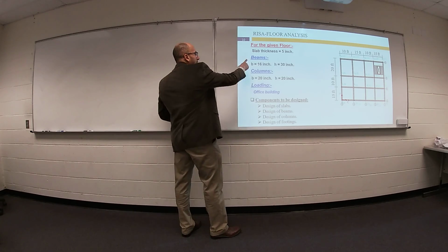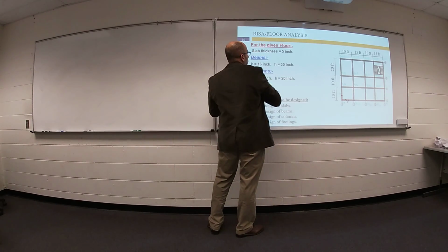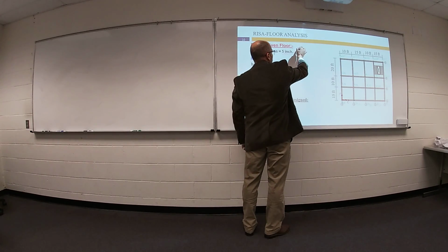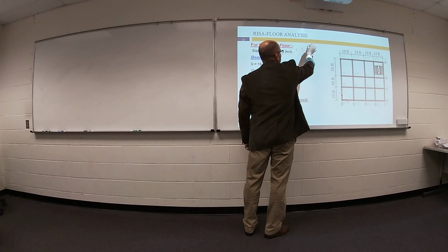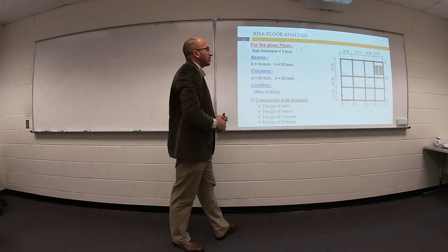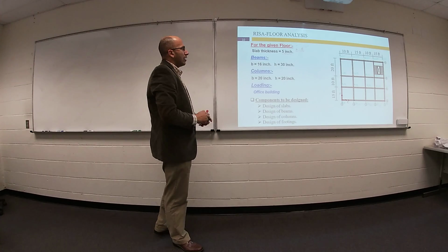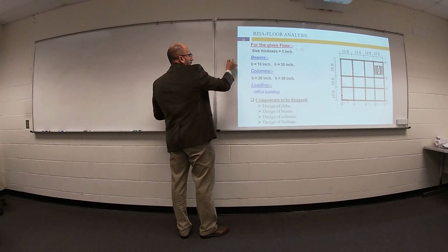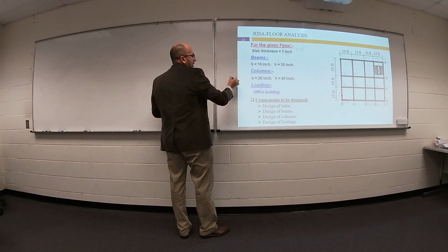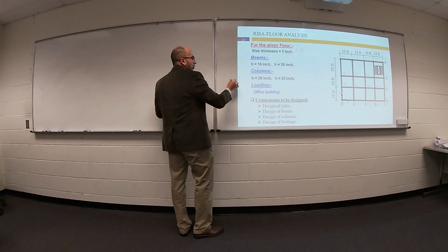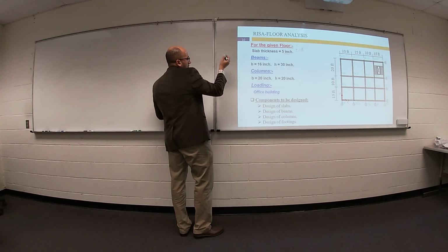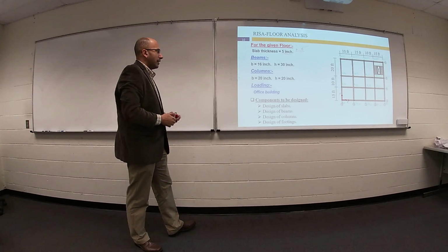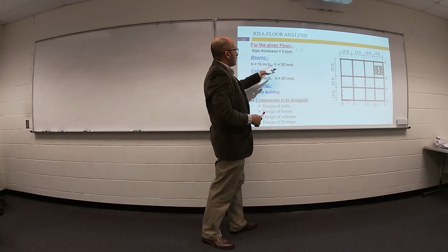We have beams. First, we have a slab with thickness 5 inch. Most of your slabs in your design are between 4 and 6 inch. Your beams: width 16 inch, and total depth 30 inch. If you remember, this width is something around 14 to 16 inch. Most of the time, your span divided by 16 gives you your depth. So in this case, it's 16 times 30.